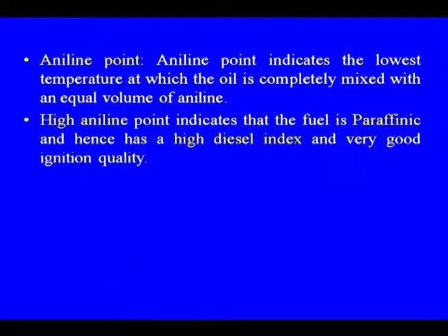Aniline point indicates the lowest temperature at which the oil is completely mixed with an equal volume of aniline. High aniline points indicate that the fuel is paraffinic and hence has a high diesel index and very good ignition quality, or vice versa.